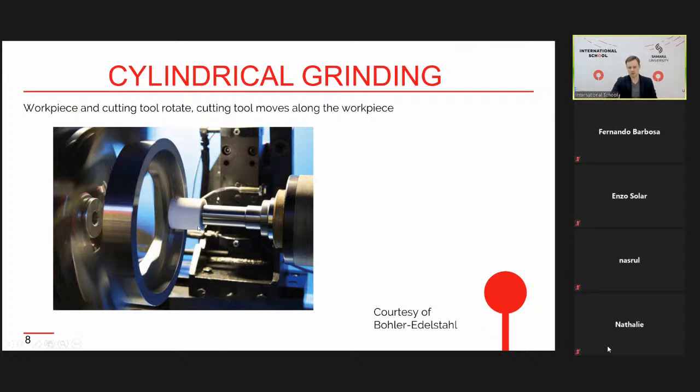And in this case, when we have a grinding tool, it also has abrasive particles that are similar to sand, and they cut very small chips. There are a lot of particles on the grinding wheel, and their size starts from some microns and goes up to sometimes 1, 2, 3 millimeters. So it's the size of these abrasive particles that cut the material. When we cut with particles of some microns or tens of microns, we cannot see the chip because the chip is also too small.